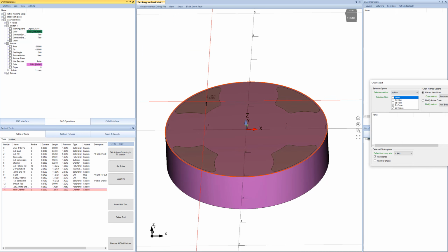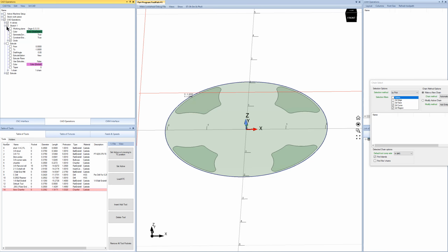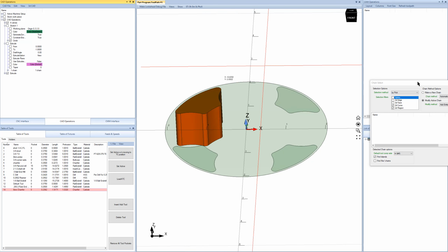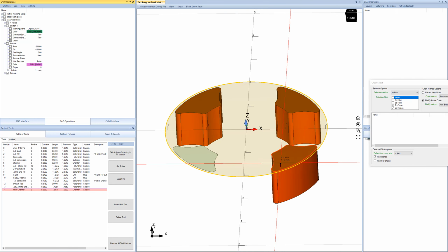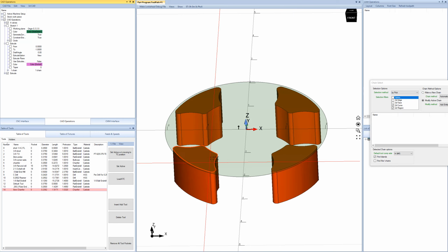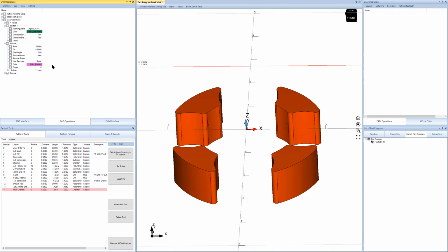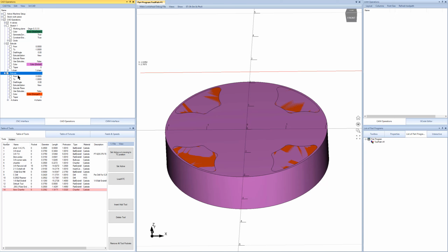And now I'm going to click on these internal shapes. And actually, let's turn off the original extrude so we can grab these easier. Okay, so we'll get that one. And then we want to say make a new one for this. Okay, so that looks good. So now what we're going to do is change some of these extrude values around in the second one. So we're going to go up instead of down. And we're going to go up, say, 125 thousandths.